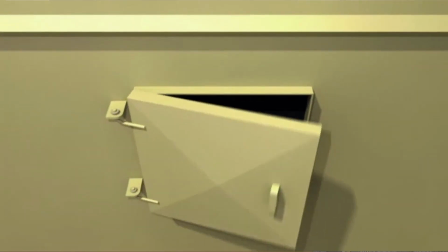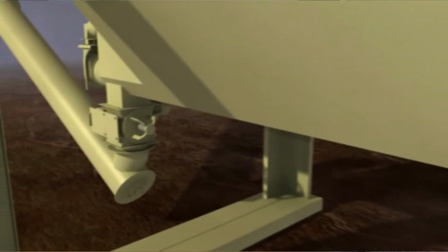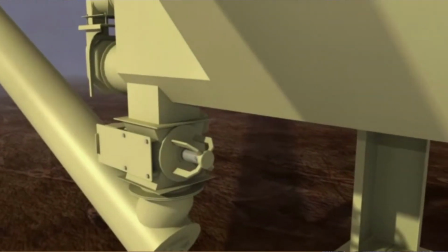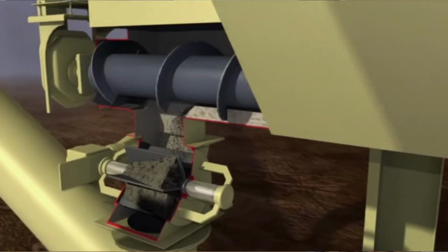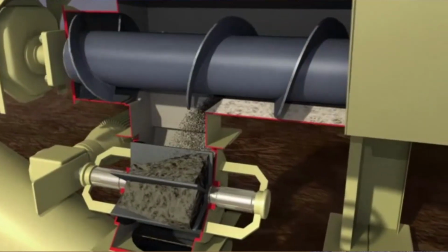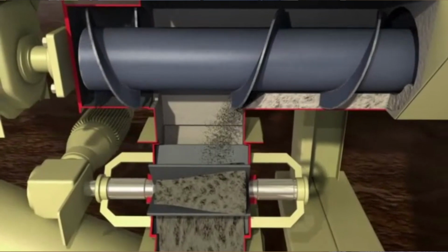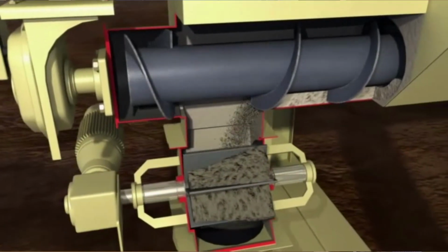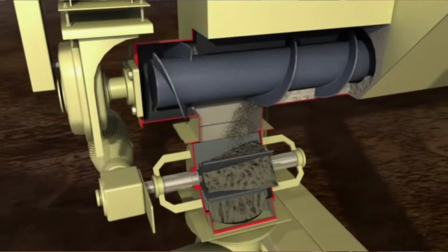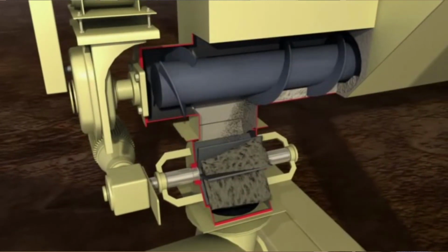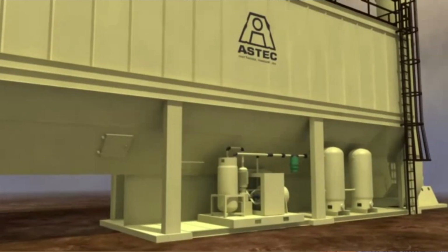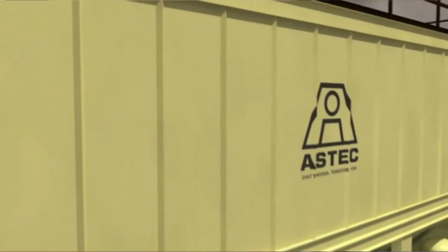As it falls down into the hopper, you can see you've got the hopper screws conveying that material back towards the drum. There can be lots of different screws on the outside of that drum. It can be waist screws, lots of different screw configurations. Here's a breakaway of an airlock. You can see that here's the minus 100s and 200s put into the airlock. The reason the airlock is in place is basically because you want to keep the air away from it. You don't want to pull that dust back out of the screw. You want to convey it to the drum. Also, it allows you to keep surging at a minimum.